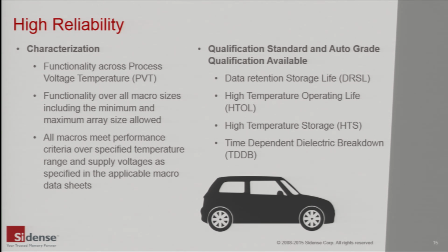Qualification tests include data retention storage life, high temperature operating life, high temperature storage, and time-dependent dielectric breakdown, TDDB. The TDDB test determines the memory retention characteristics and is often used as a proxy for PPM. The retention for Sidense OTP macros exceeds 10 years at a maximum operating temperature and at 100% read duty cycle.